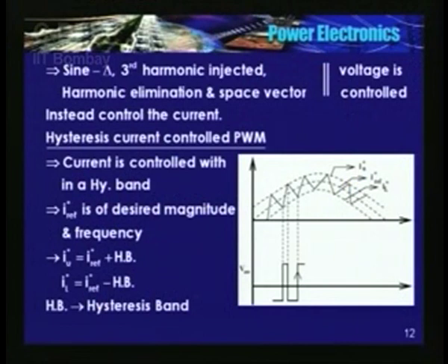So how to control the current within the hysteresis band? When the actual current touches the lower band, you close the upper switch and open the lower switch.